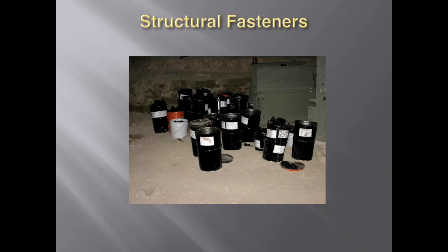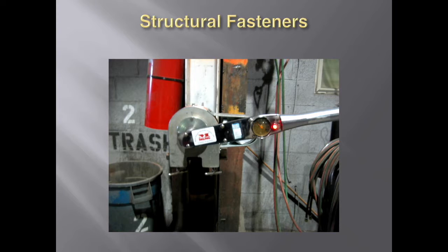So what happens in an area where there's a lot of dust, of course, it gets stuck right onto the bolts themselves. It doesn't impact anything until you go to start installing these bolts and doing rotational capacities. So when we come out on the site, we'll check the storage. These should be in an area that's controlled to where they're covered up and there's not a lot of dust. We'll come out and do a pre-installation inspection, which basically you put a bolt assembly together in a Skidmore and tighten it up, and we'll check to make sure that we meet the minimum tension, and then also that each component of that assembly is put in the right place.